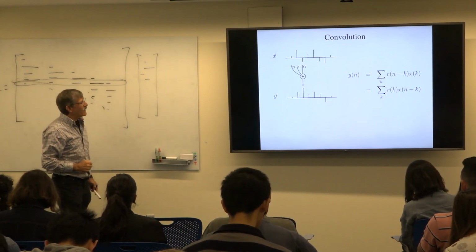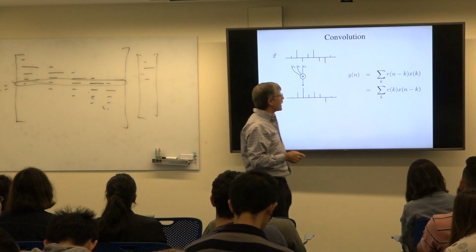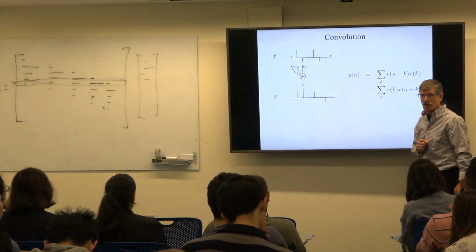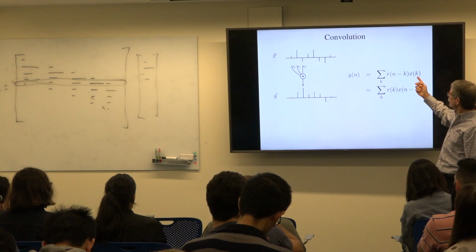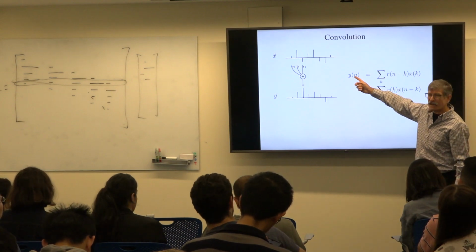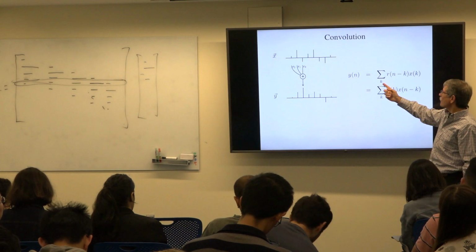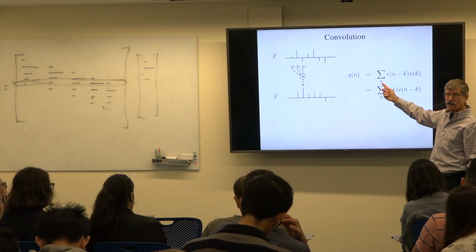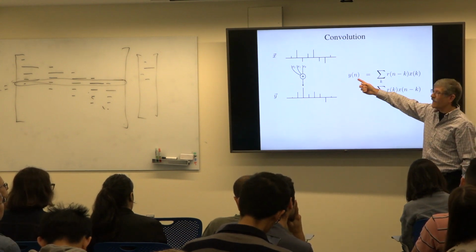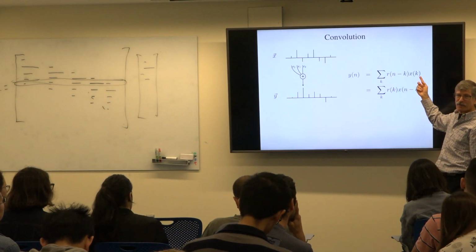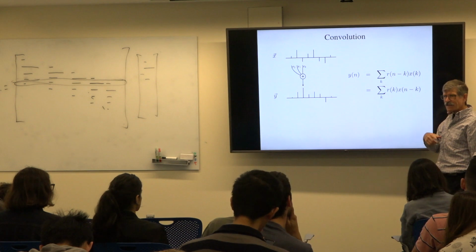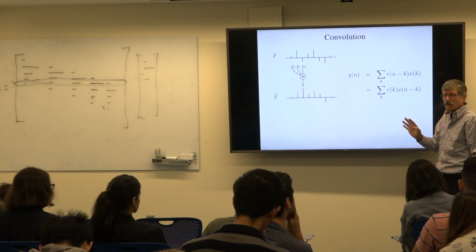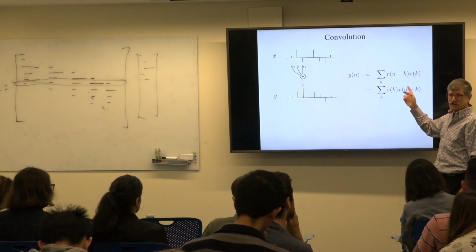The only other fancy thing is, if the x-axis is time, what k's do we sum over? And the answer is, in this perspective, where we're asking for the output at time n, we're going to sum k from 0 to n. We're not going to go to n plus 1, because the output at time n can't depend on x at time n plus 1, because that wouldn't be causal. If the x-axis is something other than time, that's not an issue. And so this is always the formula.